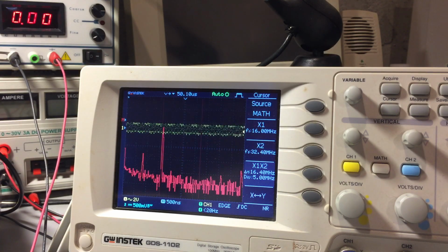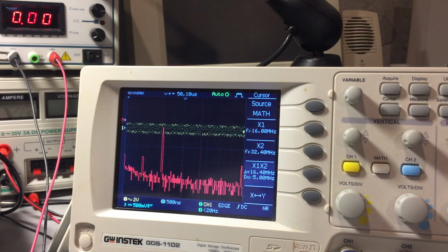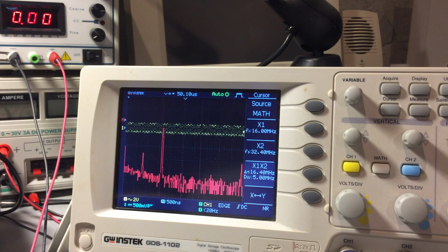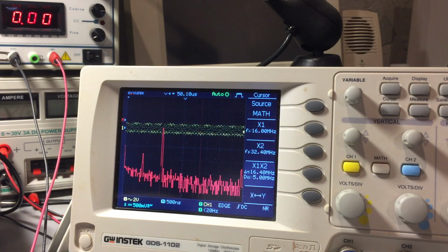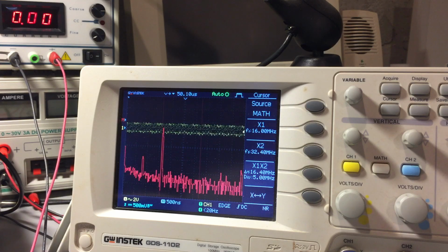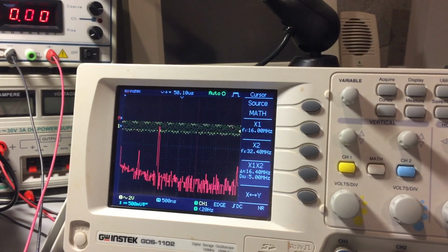I could have picked the third harmonic, would have been 24 megahertz. By the time you get to the fourth harmonic, it gets a little more challenging because the amount of attenuation by the time you get to the fourth, fifth harmonic may be too low. But clearly this method can be used for either a frequency doubler or frequency tripler. So let's take a look at the other two methods. Give me a moment to set that up.